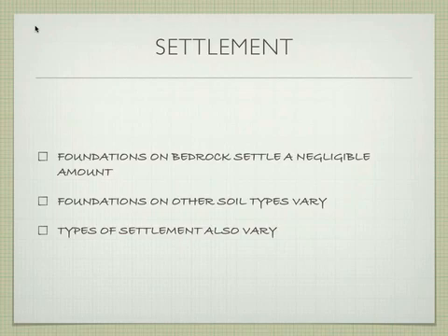So when we're talking about settlement, the idea is that over time, the placement of your foundation in elevation is slowly going to sink, because the soil is going to compact, and stuff is going to happen in the soils that allows that to happen. If your building is built on bedrock, it's probably not going to settle much, which is a good thing, which is why people love building on bedrock.